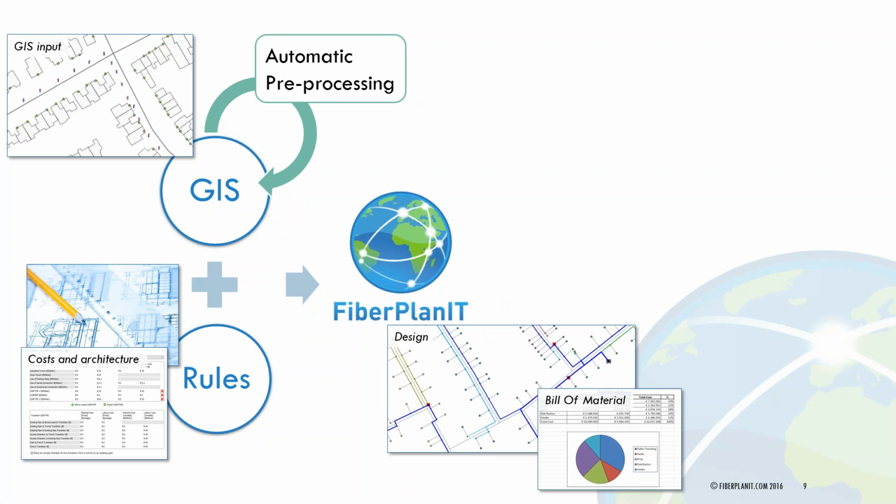So it will then tell you where trenching is needed, what type of cables and ducts need to be deployed in these trenches, or if the cables need to be placed aerially or not, and also the locations of any fiber concentration points. And all of this will be generated from the point of presence to all of the demand points, all of the buildings in case of an FTTH design.